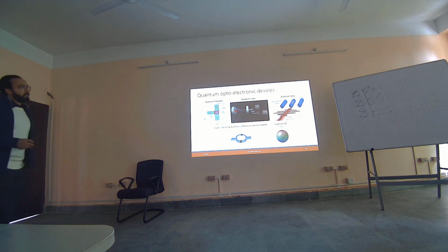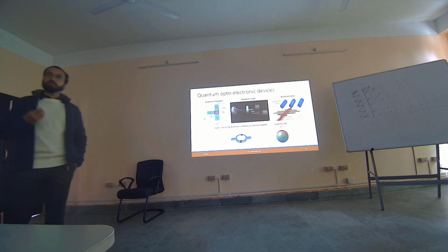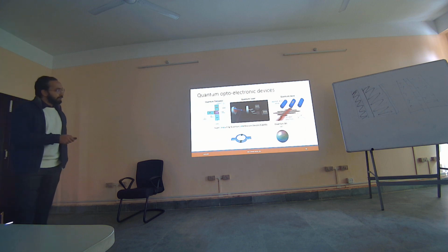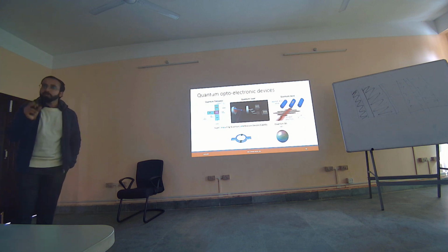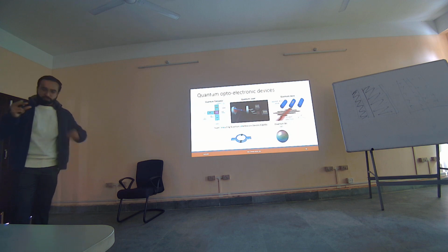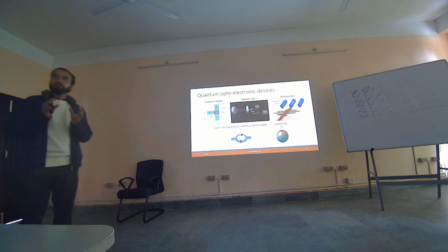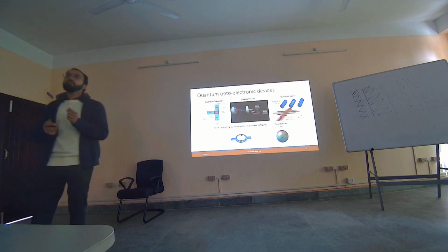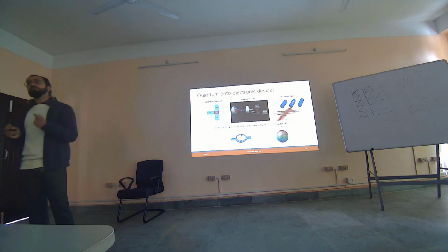So quantum transistors: these are not conventional transistors. We still have a gate, source, and a drain, but this island that you see is a quantum confined structure. Whether it is physically confined or Coulombic confinement doesn't matter. It's a confined structure, and sometimes it's also referred to as a single electron transistor.